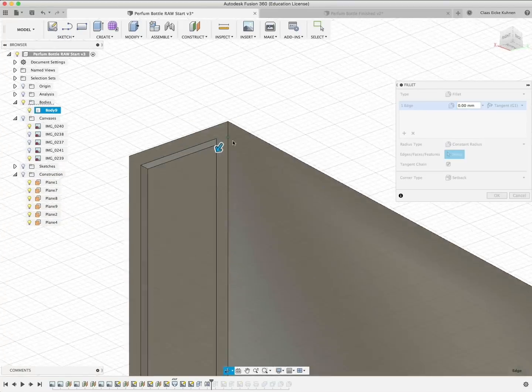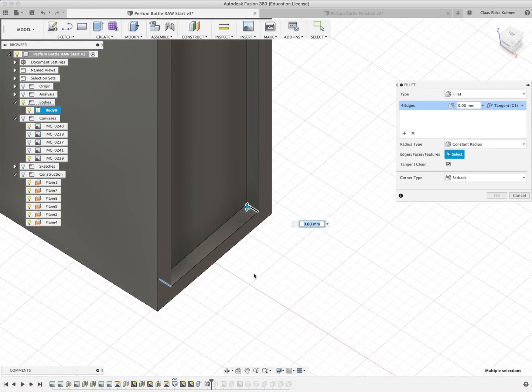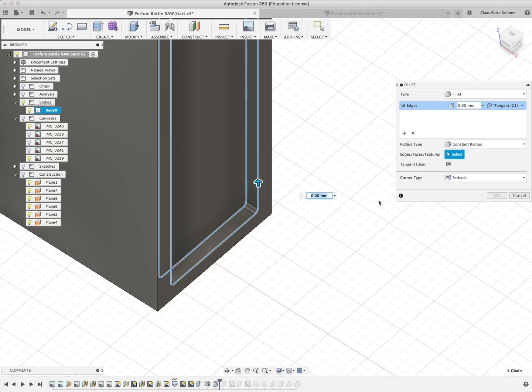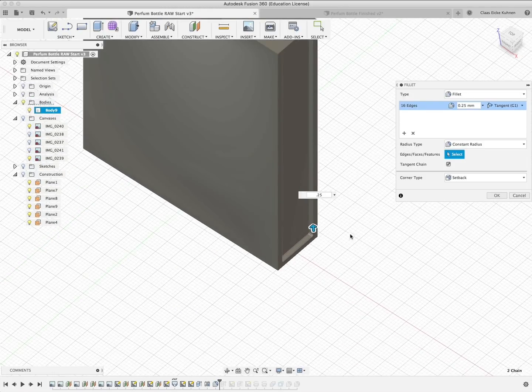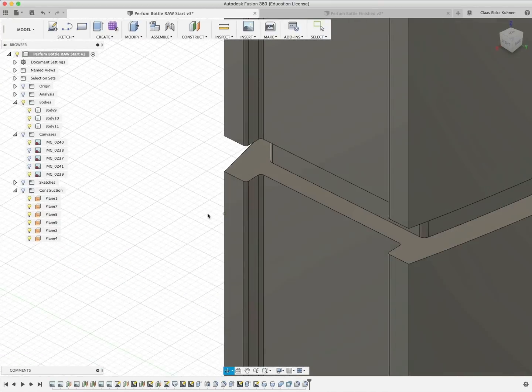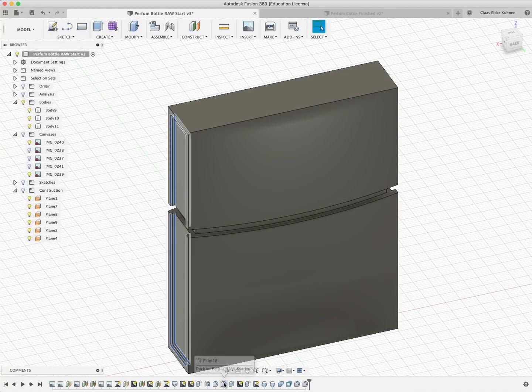Because my thought is, well, I could save myself some time. So I do this corner and this corner and this corner, 0.5. Very good. And then I do a repeat fillet and select this and say 0.25. Oops, didn't press the other key. Very good. So when I now jump back in time to the end, there this all actually works out. So you see this actually did a pretty good job, but the problem is I have now here some fillets and there I have some fillets. So how do I structure actually the design timeline?